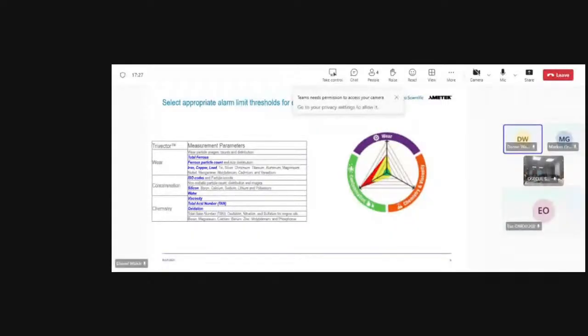However, even though you have all this information, when people start to do alarms, rather than alarming all of those 75 parameters, they tend to focus on very specific parameters to start with, and then make sure that they have very good alarms around those key parameters, which are indicators of problems.